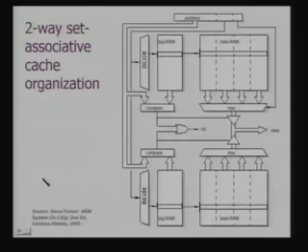In a typical ARM implementation, if we have a two-way set associative cache, you see that this organization is very similar, just like that of your direct mapped cache. Instead of one block, now we have got two blocks. This is a two-way, that is why we are calling it a two-way set associative cache. The decoder, that same index part, is used to find out the block, and this tag is now compared with the address part. So, it can be either here or it can be in this block.